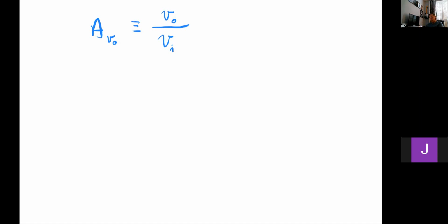So we're going to apply that idea later on, okay? So let's just look at this on its own merits, as shown in figure 8.28, and try to find the voltage gain as well as the output resistance. Looking at the figure, it's pretty trivial to see that the output resistance is the transconductance of transistor 2 times the output resistance of transistor 2 times the output resistance of transistor 1.